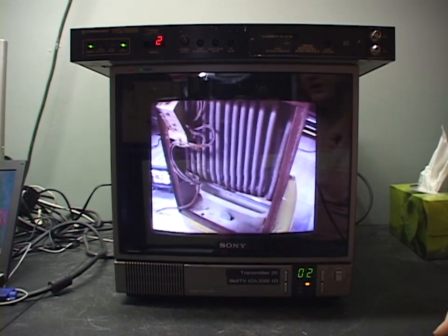So something about like that. Now you may notice, the picture's looking a bit fuzzy right now. I've added another inline 20 dB attenuator, so the signal's now being attenuated by 40 dB. And the RF level's turned all the way down, so it's a bit fuzzy, but I can demonstrate here if I turn the RF level up. Clears right up.